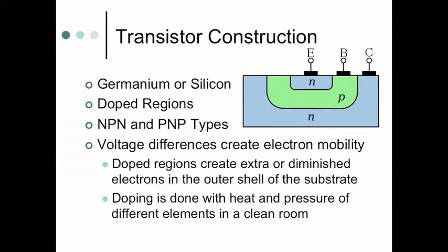And they use photographic processes where they take a photograph and shrink it down of the circuitry, shrink it down, and use that to put a resist layer on the silicon. So when they dope in different elements, it only goes into certain spots.